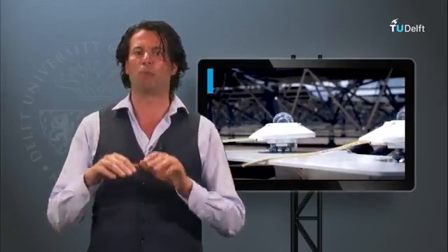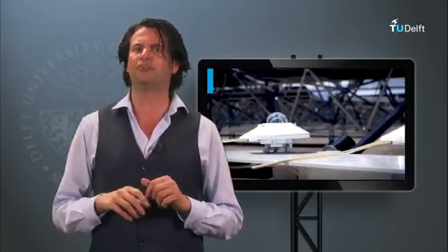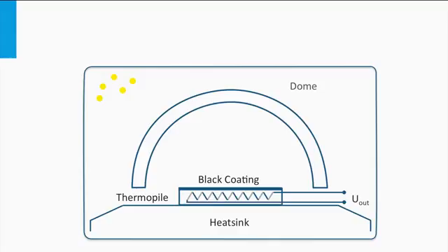A pyranometer has a field of view equal to the complete hemisphere and is sensitive to the full spectrum of solar radiation in the range from 300 nanometers to 3000 nanometers, and has a flat spectral response in the whole range. It allows us to measure the radiation very precisely, independent of the wavelength of light. It measures the thermal effect of the radiation.